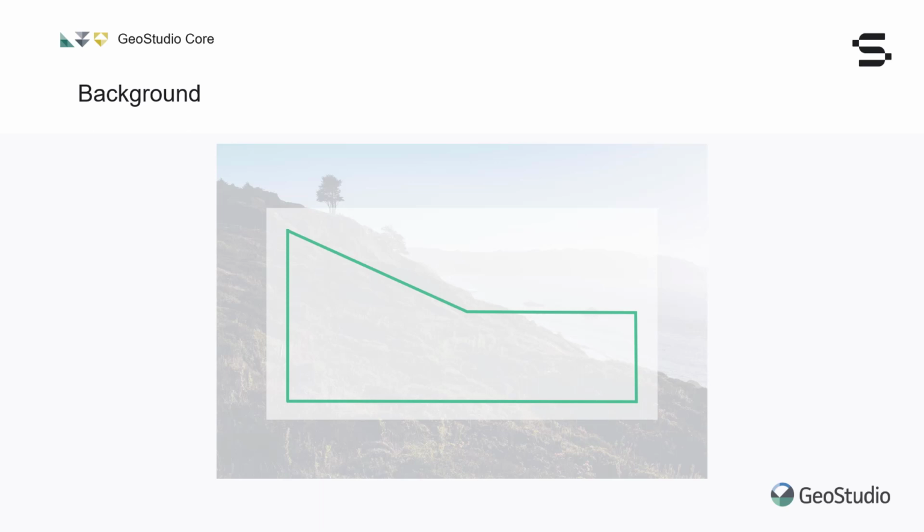To better represent the problem and be able to properly answer the question, we might have to consider the water conditions that exist in the slope. Where's the water table? How does it affect shear resistance? We might also need to consider if there are stress and strain conditions that affect the slope as well. Once all of these elements are considered, then we can begin to answer the engineering question and proceed to a slope stability analysis.